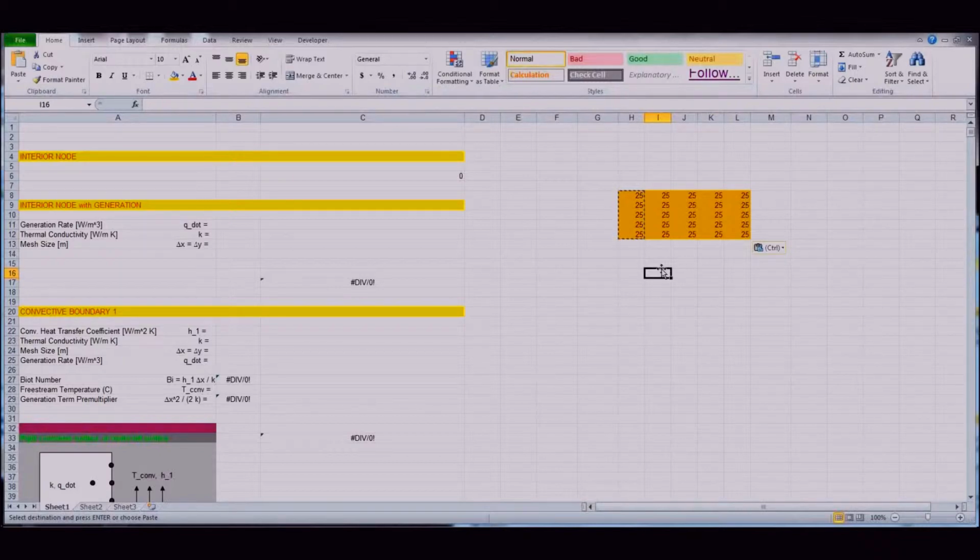Another thing: once you're running the Excel spreadsheet, you push F9 to make it go and do the calculation. You'll see down in the bottom a display showing how many iterations it has gone through, and we'll look at that later when we solve a problem in a later segment. So we begin by setting up our grid, knowing delta x and delta y, and you enter in values to begin with. Once you've done that, you might want to color the perimeter, whatever the perimeter conditions might be.